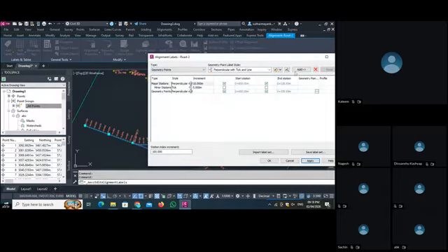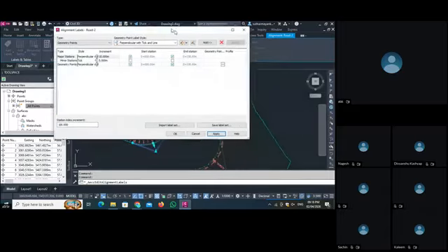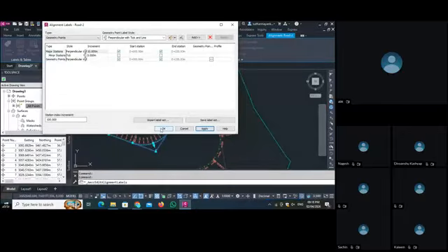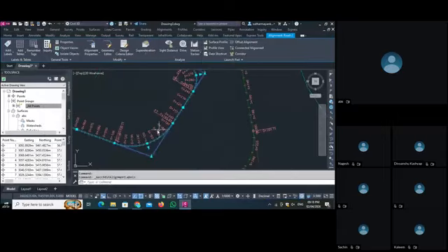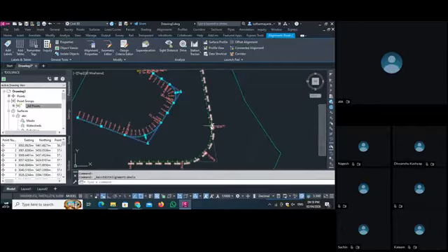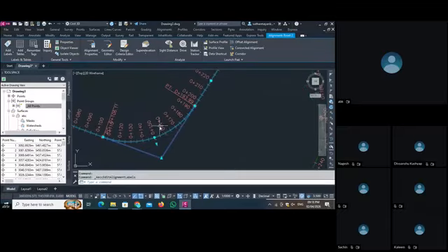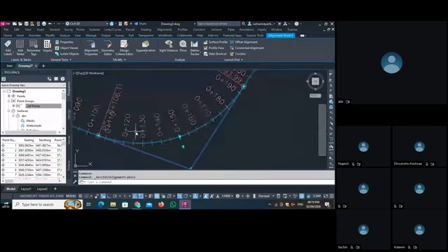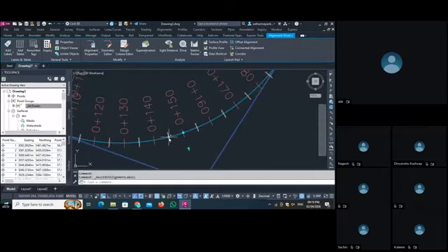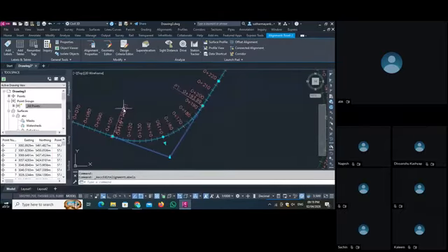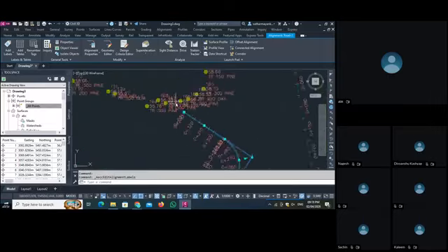I apply it. So as I apply and do okay, see, this is all the set automatically created when you choose all the labels. And when you don't have any label, I showed you how to add labels manually. See, these are all the major labels at every 10 meter of interval. These are all minor ticks at every 5 meter of interval, and this is the curve tangent we added, starting point, ending point, and the starting point here.